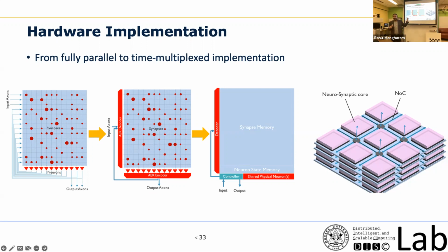So it's a lot of conversion happening at scale. At one level, you have the analog neurons generating spikes, which is purely in the analog domain. That is converted into a digital packet that is routed across the network on chip. Once the spike reaches the destination, it is converted back into an analog spike, an analog voltage, and given to the particular neuron. That is why all the analog to digital conversion comes in. And there is some accuracy loss in converting a spike into digital.